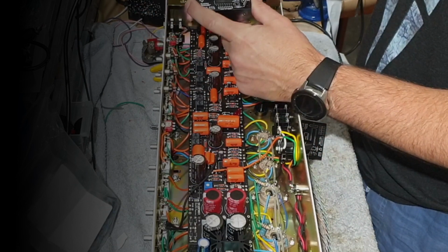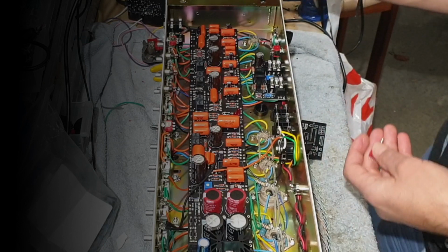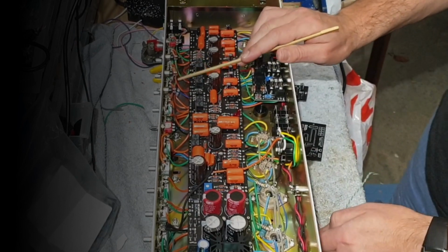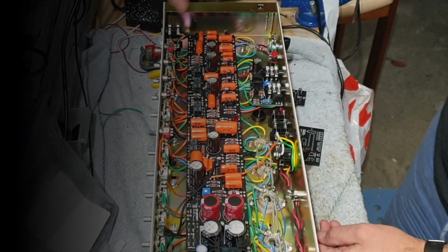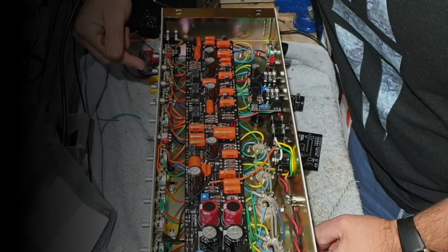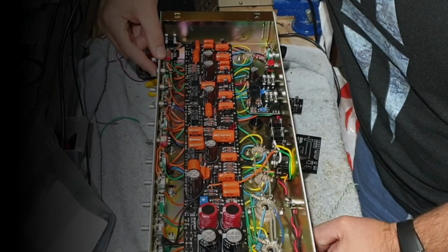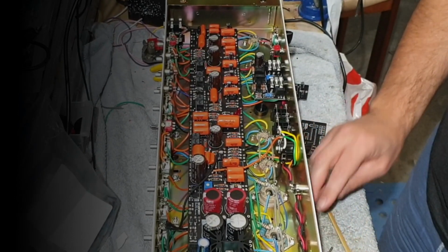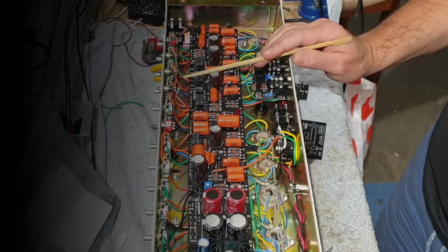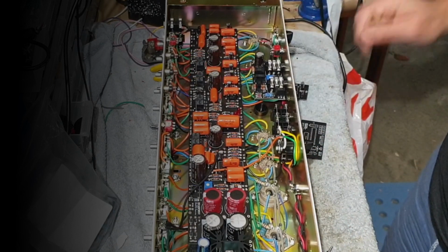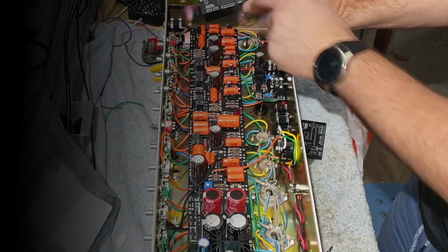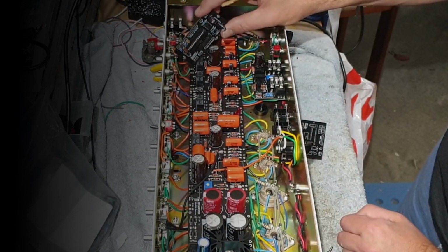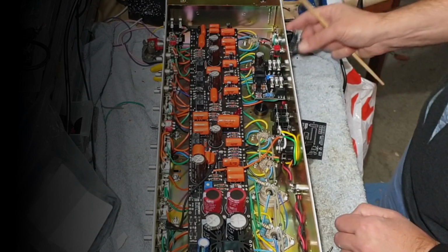And then obviously with MIDI, you can store those as presets, program change messages. Okay, so you've got to have one side of your momentary switches grounded. We're using these push buttons. These push button switches are pretty cool. You can use any kind of push button you want, really, but I've settled on these after trying a few different ones. I think they look pretty cool. You just wire from each side of the switch to the input functions here, and in turn we'll wire from here out to the relay controls, which is R2, R3, R4, as I said, respectively.